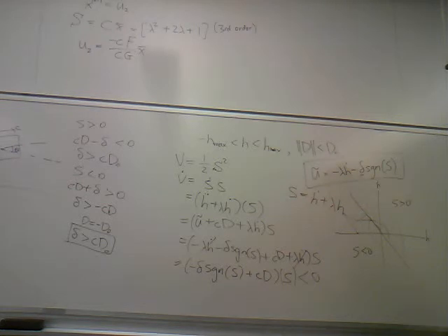What if you just see something where it circles into the origin or something weird, rather than sliding along the surface? So in sliding mode control, we're basically setting it up so that it will slide along the surface. Of course, you could do something else. That would be a different type of controller. And the great thing about this is that for a second order system, we can follow the trajectory of a first order system. And for an nth order system, you can always follow an n-1 order system.